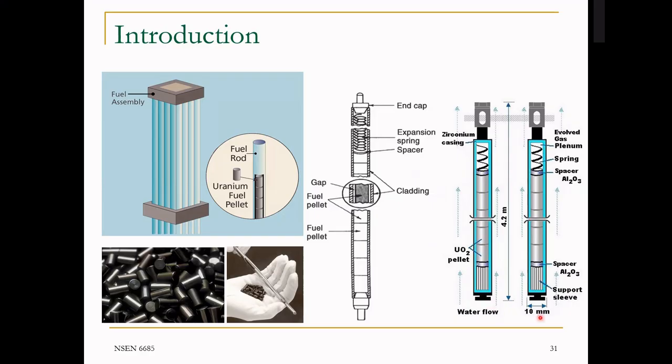But again, this is multiple rods, right? As part of that fuel assembly, fuel pellets, spring is loading over them. This is called the upper plenum. And again, the reason for the upper plenum is to collect the fission gases. We filled that originally with helium for light water reactors or other materials such as sodium for advanced reactors. Then the coolant is going into the sub-channels between them. Okay? So this is just more highlight on a single fuel rod construction, how it looks like.